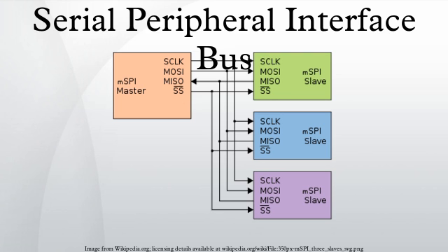Standards: the SPI bus is a de facto standard. However, the lack of a formal standard is reflected in a wide variety of protocol options. Different word sizes are common. Every device defines its own protocol, including whether or not it supports commands at all. Some devices are transmit-only. Others are receive-only. Chip selects are sometimes active-high rather than active-low. Some protocols send the least significant bit first. Some devices even have minor variances from the CPOL-CPHA modes described above.